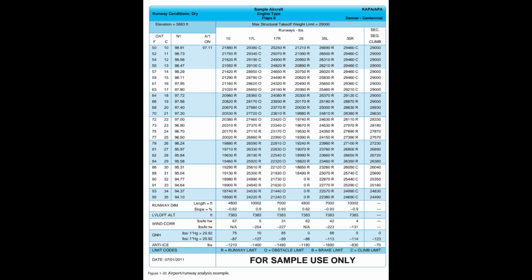Graphic depiction of the OEI procedure is often available to give the pilot a pictorial representation of the special OEI procedure. An engine failure during takeoff is a non-normal condition. Therefore, the actions taken by the pilot, including the use of an OEI turn procedure, take precedence over noise abatement, air traffic, SIDs, DPs, and other normal operating considerations.